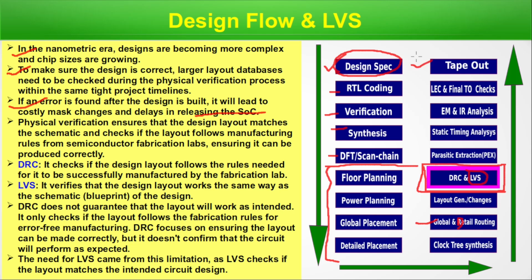Building the mask is a costly affair. Time-wise, material-wise, it's very expensive. Before tape out and before making the mask, we have to make sure that the design we are taking towards tape out exactly represents what we have intended. That means the design specification is perfectly translated into the mask or layout. LVS is one of the ways to check this.